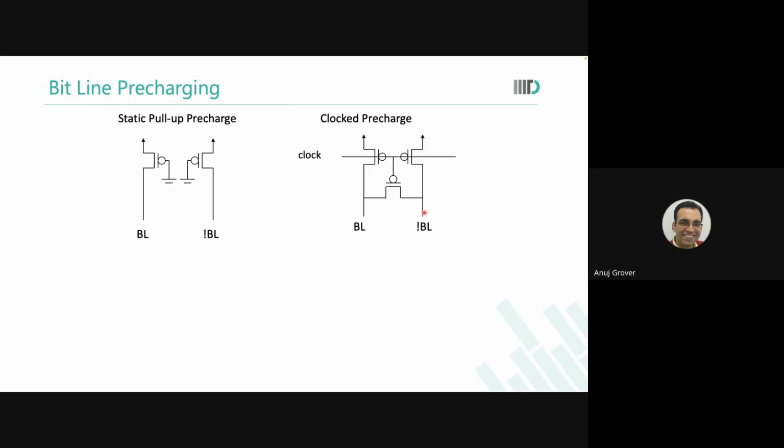In the same way, in the write cycle, first the precharge goes off, then the write driver turns on, then the bit lines get 0, 1, then the word line comes, then you write into the memory cell, and then you close. It is the same cycle. It is just the sequence of operations. State machine. Which state you move from this to that to that to that. Is that okay? Clear?